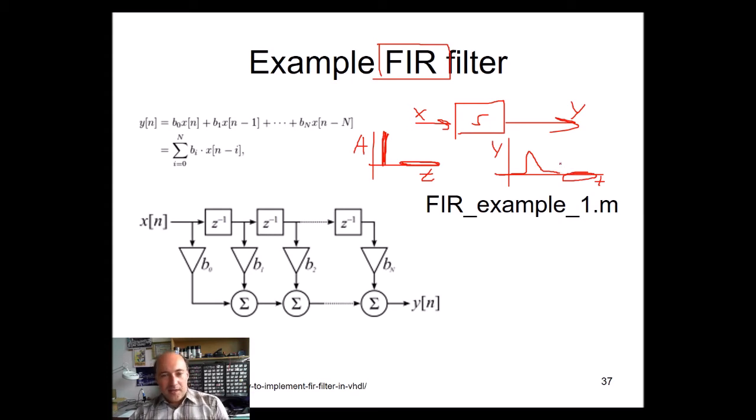It may sound complicated, but mathematically it's quite simple. Mathematically it is this formula, and you can see that it's nothing else than a sum. So it's basically the same equation as we have seen for the last filter. It's some coefficient b, that's this b_i, and those are the samples that we have somewhere in the memory. And here this y, this is my output signal.